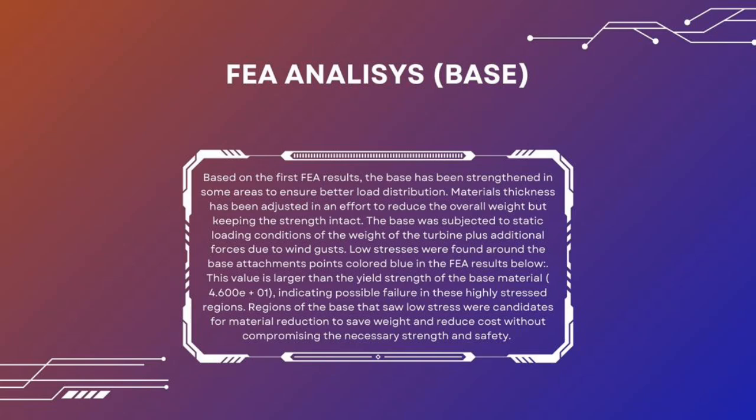FEA analysis, base. Based on the first FEA results, the base has been strengthened in some areas to ensure better load distribution. Material thickness has been adjusted in an effort to reduce the overall weight while keeping the strength intact.